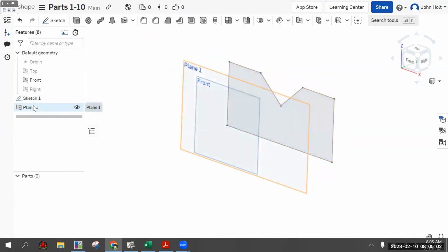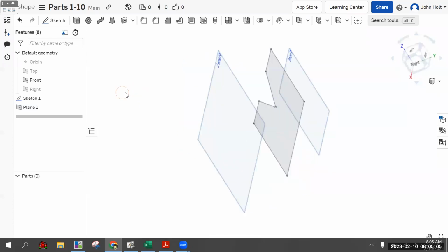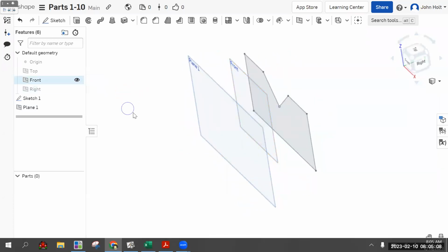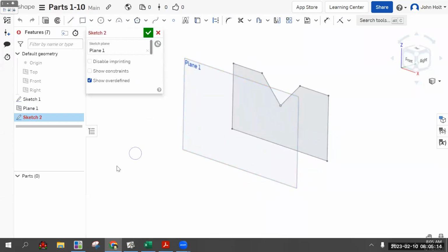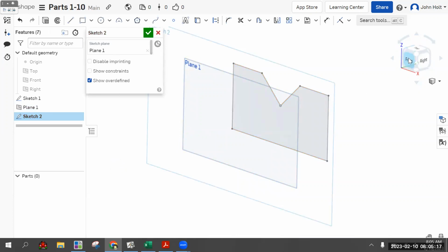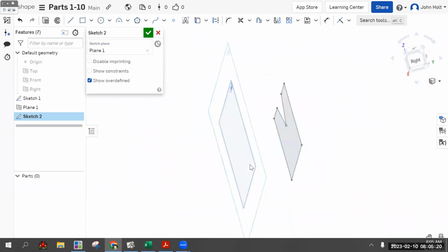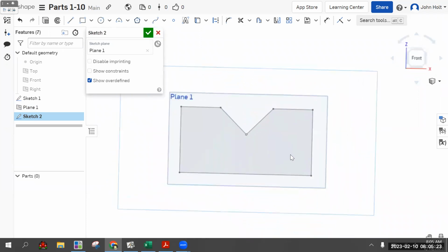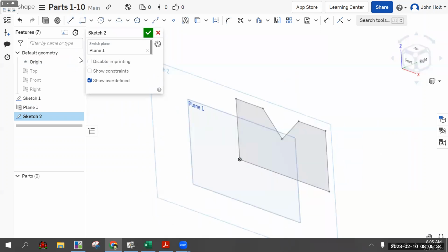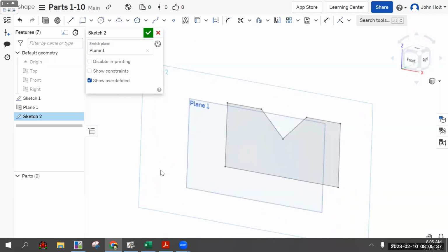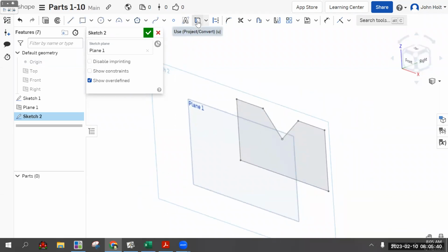And check. Okay, so our most recent thing is creating that new plane. And it's far away from the origin plane. We'll turn off the origin front. So now we need to put a sketch on this new plane. And we need to draw the front. We could try to line it up exactly and dimension it off the origin, but we don't have the origin on our new plane because we're off. What we're going to do is use the use tool, which is also project geometry.